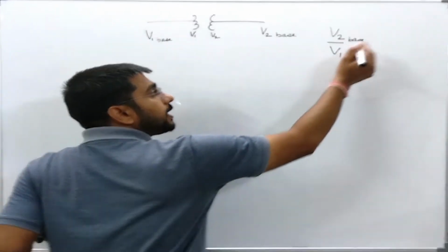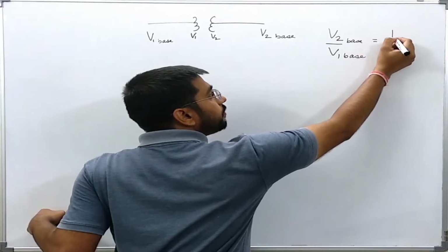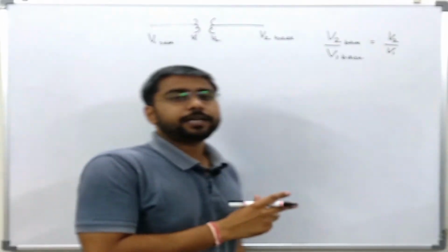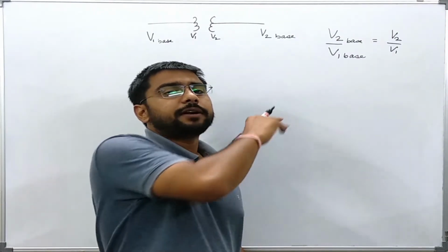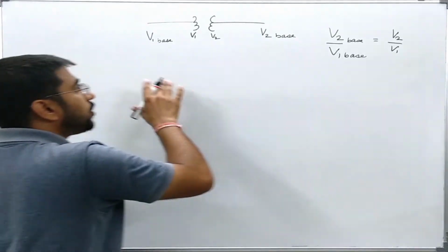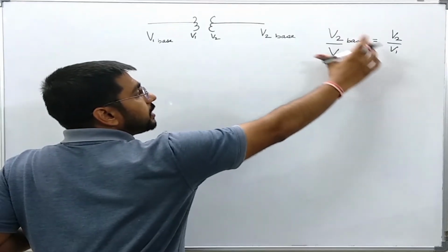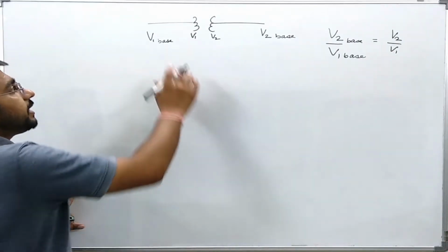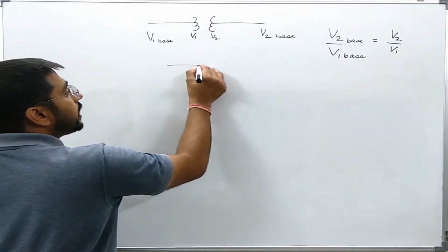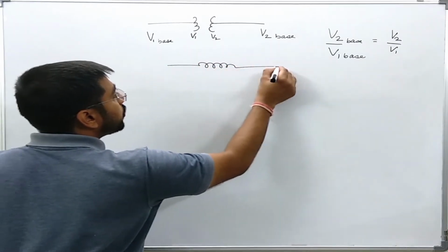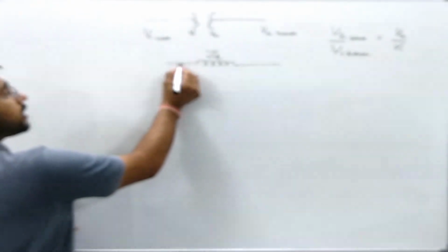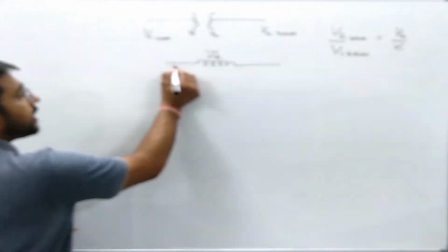Whenever this equation is holding, then we do not find any difficulty in using the per unit system wherever a transformer is present, because whenever the transformation is in the same ratio as that of the base voltages, the transformer is just reduced to an impedance equal to its leakage impedance. We do not have to worry about the voltage bases. I can take the per unit system directly.